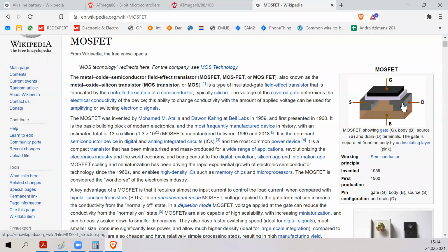So this is a fun fact, that old microcontrollers have bigger transistors, so they consume more power and run more slowly, but their leakage is much lower than the newer chips, and especially at high temperatures. At low temperatures, there's almost no difference, but you heat up the MOSFET, and the leakage current for smaller transistors becomes really, really big, 20 microamps. It's 20 times bigger than at room temperature.